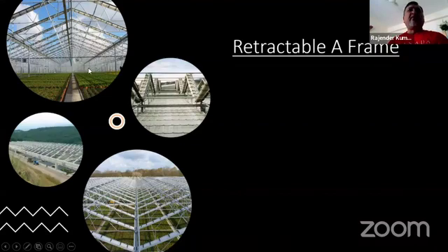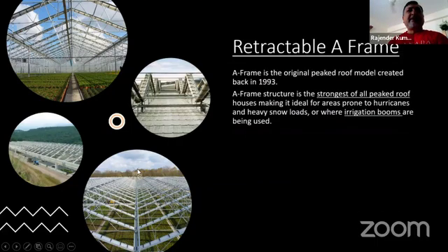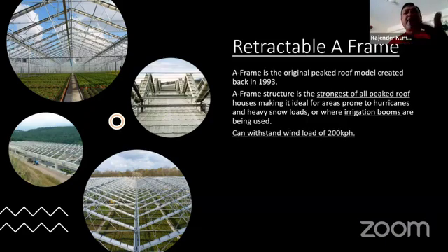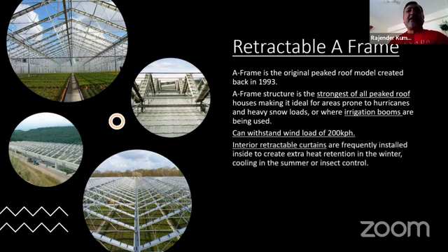A-frame is a top model actually, which is the most rigid structure in the retractable roof category. So it is one of the oldest structures also. And normally this type of structure is installed in very high windy areas, just like in the Western Ghats, where wind speed may cross 200 kph, or in high altitude areas where you have snow, like in Simla, Manali, or Srinagar.